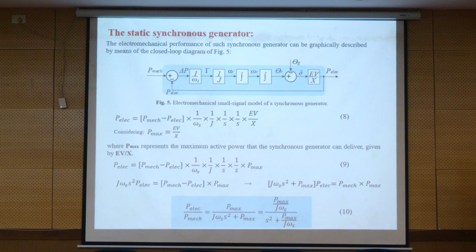For example, in a circuit breaker with 800 ampere, when a short circuit happens, the short circuit current goes to 60 kA. It's like, I don't know, 75 or 80 times more. So this actually needs a different analysis from small signal. But for the dynamic changes, this transient operating condition, we consider the small signal analysis. So, any questions so far? No? Okay, good.